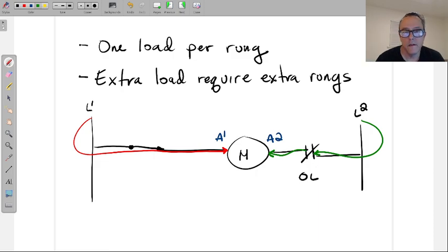That's an overload. In the world of motors, they're machines that are moving parts. Things are moving around. So things can get jammed up. The machine can get stuck. Something got jammed up in the machine. And now the motor is struggling to turn and struggling. And the amperage is starting to go up and up and up internally in the motor. In other words, it's just simply struggling and creating too much amperage.